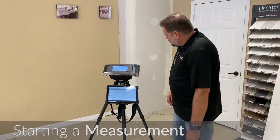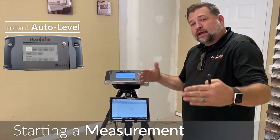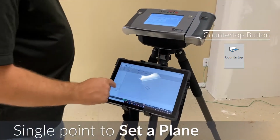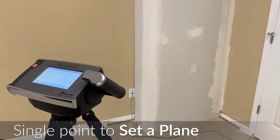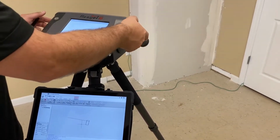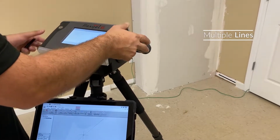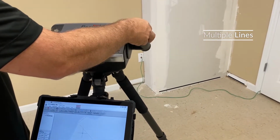All right, so the first thing we want to do, guys, is this really nice feature, auto level. We can see, because we're doing a lot of planes, stuff being plumb, vertical, and horizontal surfaces. So I'm just going to click on the measurement tab, and we're going to call this a countertop. We're actually going to rename it hearth, and it allows us to take a point. Then I'm going to hit a function called multi-line. And guys, we're going to go ahead and shoot where it goes, 2 points on each surface, and that's going to give us our hearth. And that's what we're going to build from.